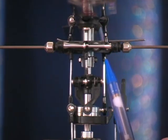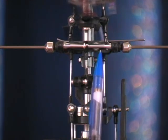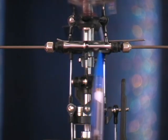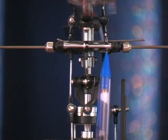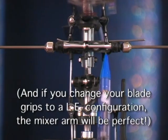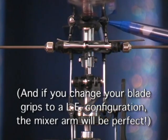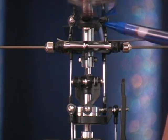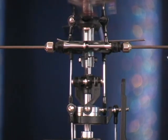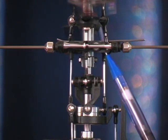Now, as I was going through this, I noticed that this mixer arm is really incorrectly positioned according to the instructions, and this is the way it's assembled according to the instructions. But really, to keep the rule of 90 degrees, this mixer arm should really be flipped so that instead of drooping down a little bit, it should slope up a little bit, which will keep the angle 90 degrees to this push rod. Now, it's not that big of a deal practically, but if you want to make things really, really right, go ahead and flip this so that it angles up a little bit.